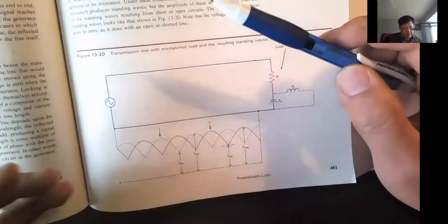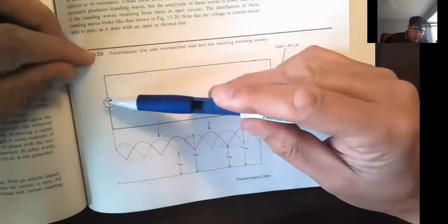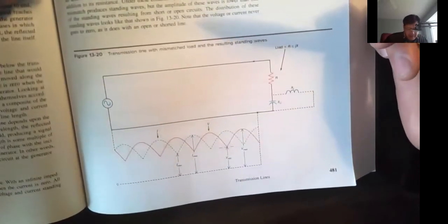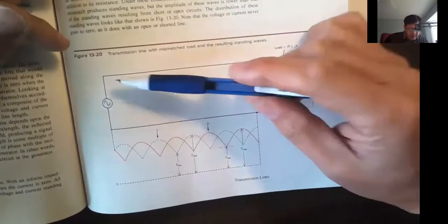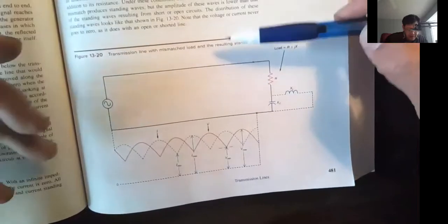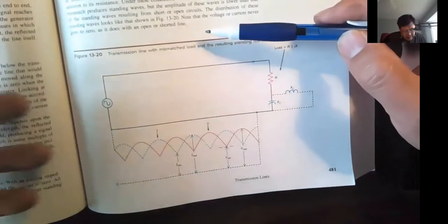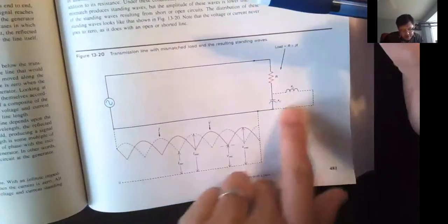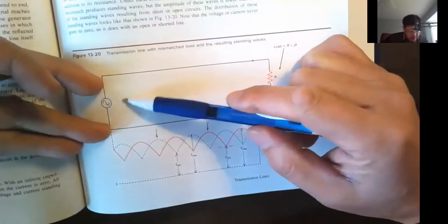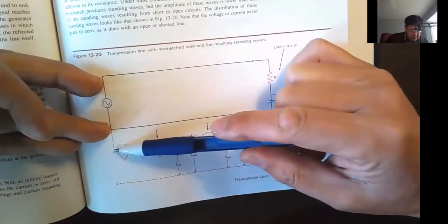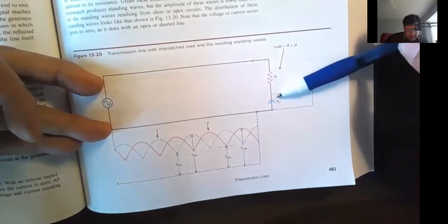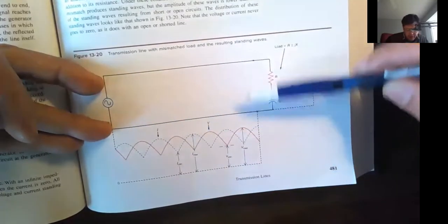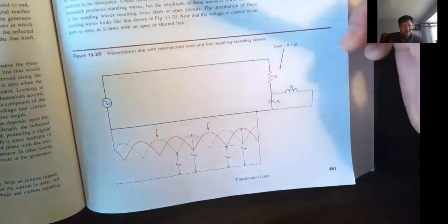So now, instead of thinking this circuit has two components, the load and source, we now have many components in between. These components are inductors and capacitors. If you have AC power energized on one side, you have oscillations all the way to the load. So as far as the source is concerned, the impedance the source sees is different from here. It's something else, because of all the inductors and capacitors we are dealing with when the signal travels from left to right.